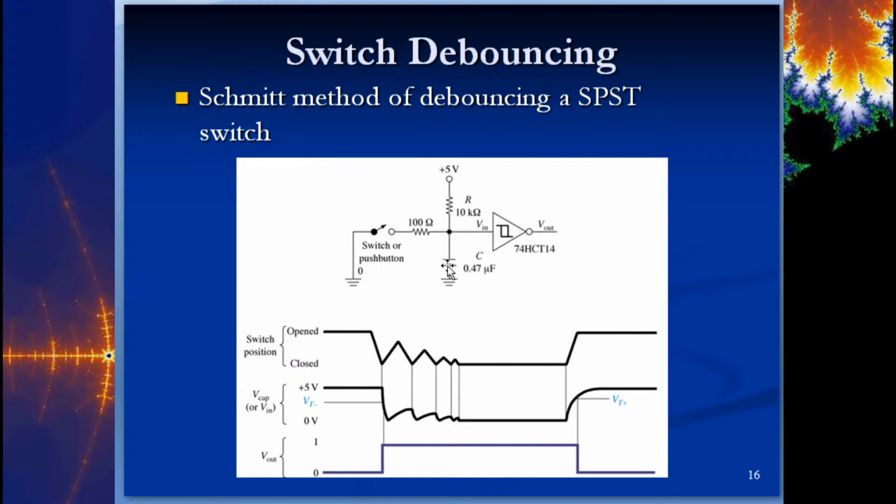All right. So initially, it's going to be high. The V output is going to be low because this thing is going to be charged high. When you want to switch it and you click over here, now this thing can come down to ground over here, right? Because it's just going to take this resistor over here because it won't be able to flow through this capacitor, because this capacitor is charged to 5 volts.